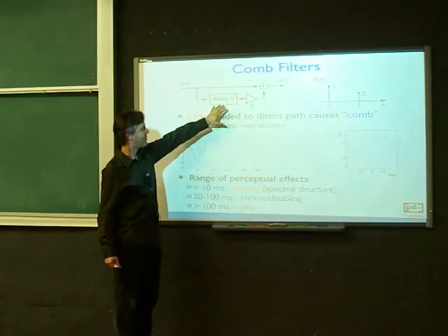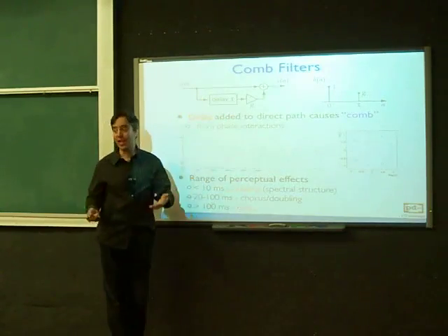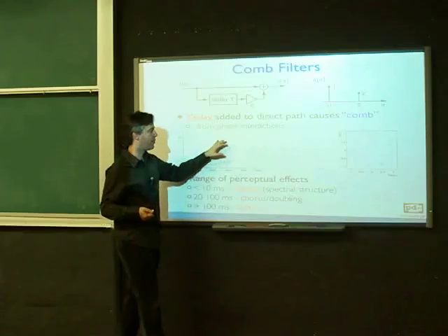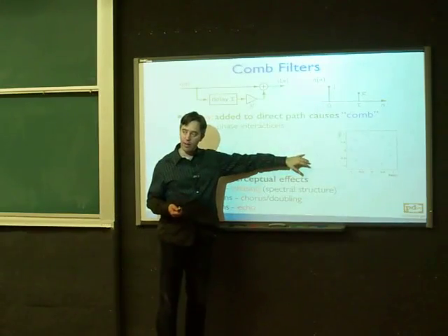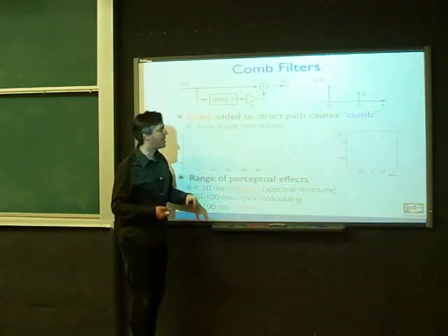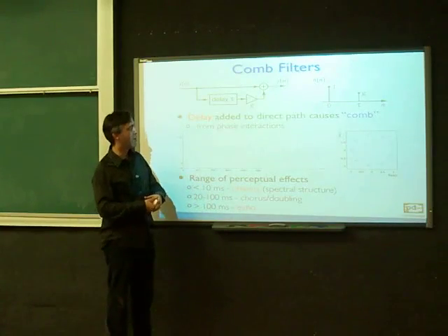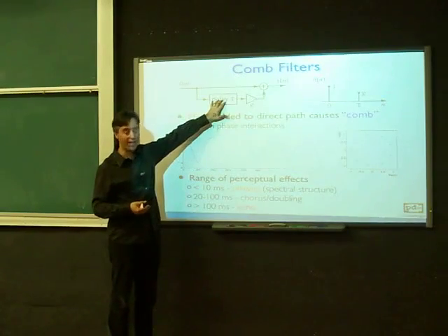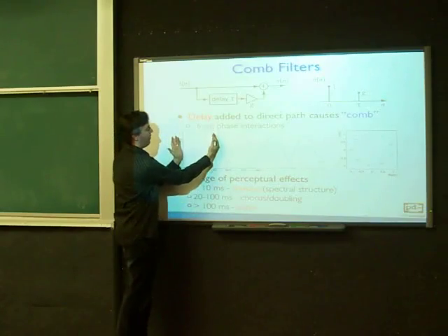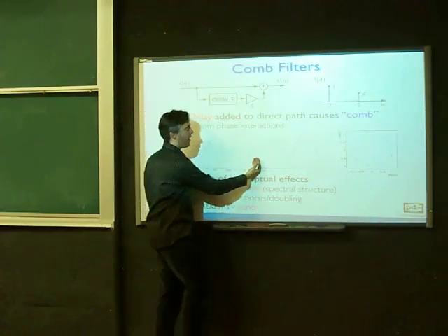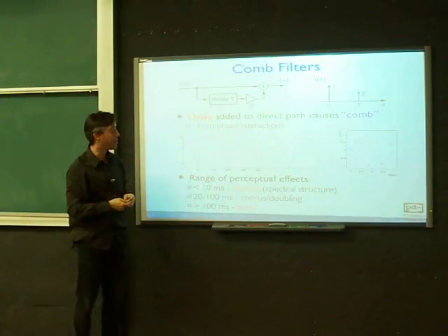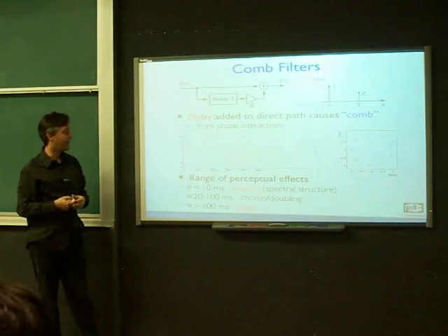If we have a system which involves delays which are not single sample but multiple samples, then what we end up with is a system which has a repeating frequency response. Basically, if this system was running at a lower sampling rate, with one sample per delay step, it would have a frequency response that looks like this. But we're looking at it at a higher sampling rate, and so we see the periodic repetitions of the frequency response, which are intrinsic to the discrete time axis.